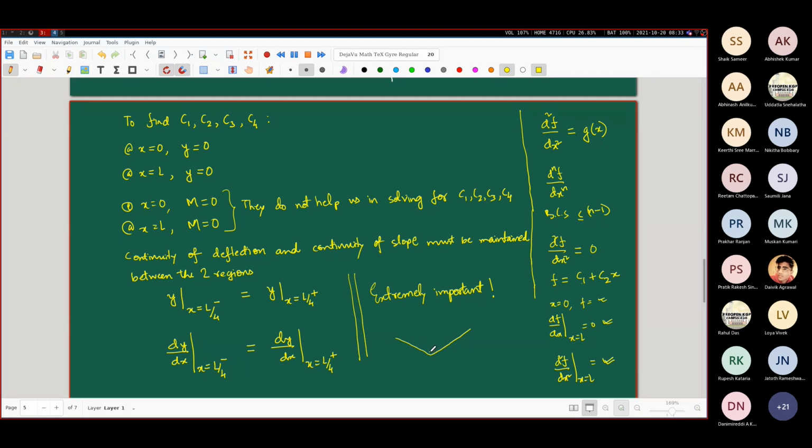This is presented to the students, and I am presenting to you right now, as an empirical fact that this is never observed in practice. We can go about trying to do these things in a very formal mathematical fashion also, but right now this is not the time and place. So please accept this as an empirical fact: in a real beam, you will never see the deflection changing abruptly like this at a certain point.